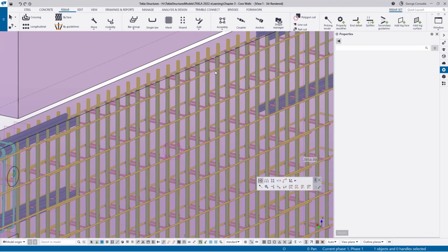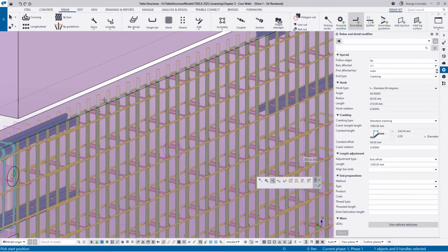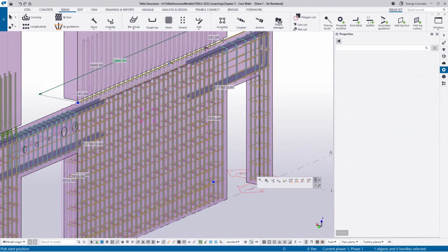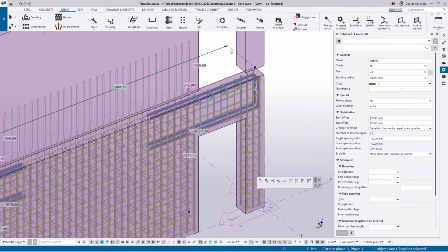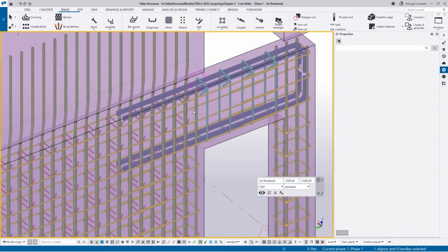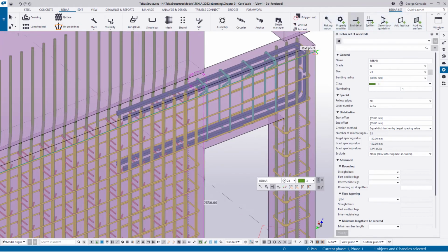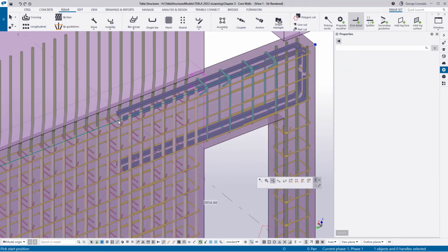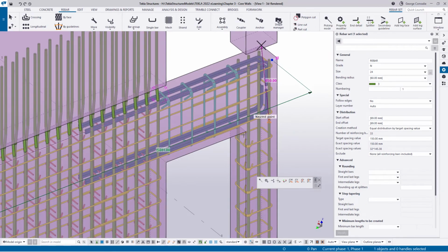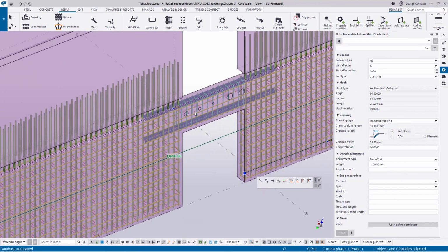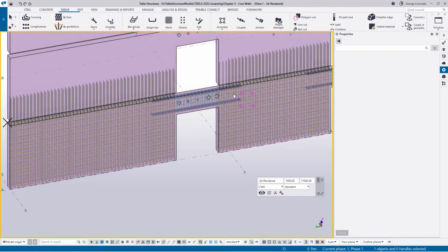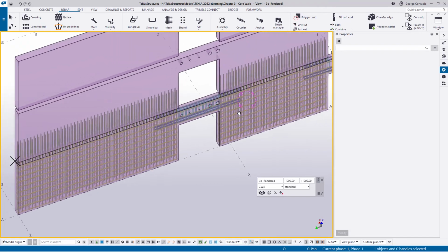If I click the inside ones, click on the edge modifier, hover over that edge, that takes care of that part. And then just make sure if you hover over that it actually just covers the range. So we can just grab that arrow, bring it up to the inside of this door. That's it. And then click on the inside edge modifier over the edge there. That takes care of that. Again, just hover over that. Grab this arrow to the inside of this door, and then make sure that this area is also to the inside of this wall. So that takes care of those.